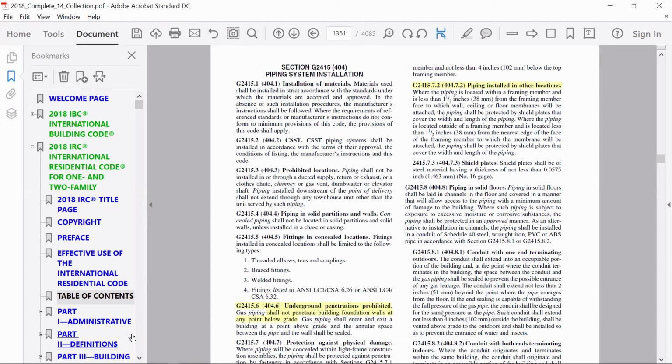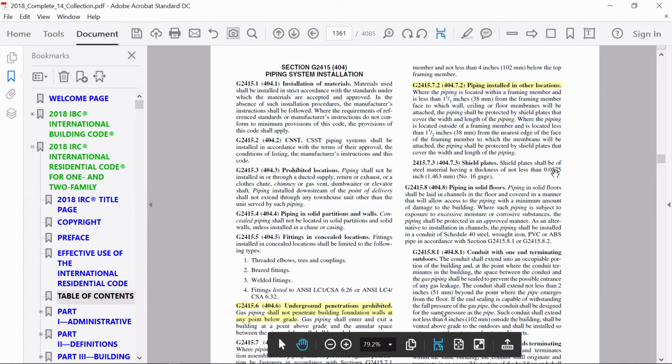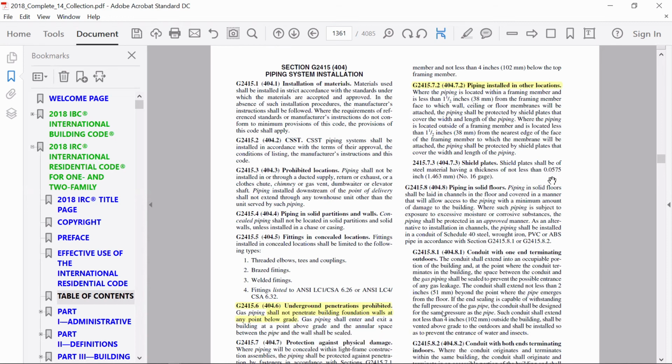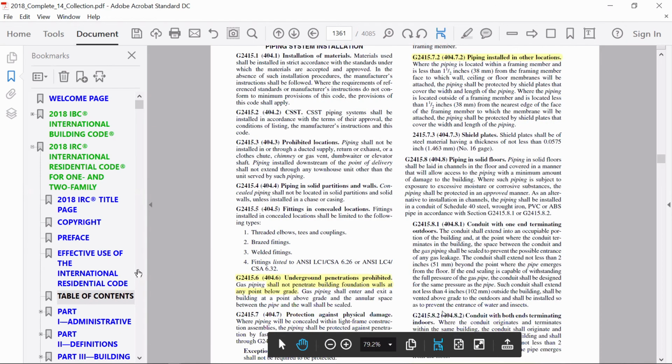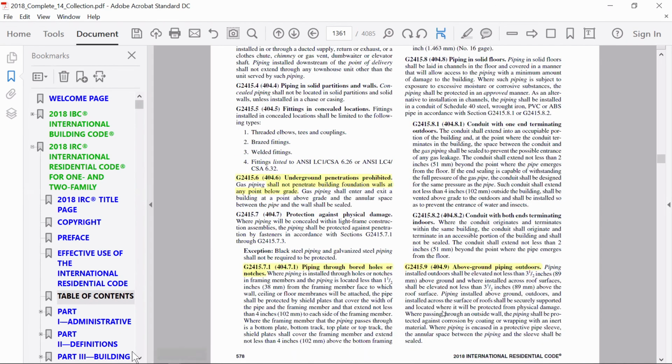If you are to bring in combustion air for a mechanical system, sure, there's maybe more than one way to do it. But if the only way you can do it is to go into a cavity wall, don't make it an exterior wall for sure, because at that point you're into insulation, things of that nature. But when it comes to the safe operation of mechanical appliances, believe me, the energy code does not override any kind of safety features and functional operation of mechanical appliances. Okay?